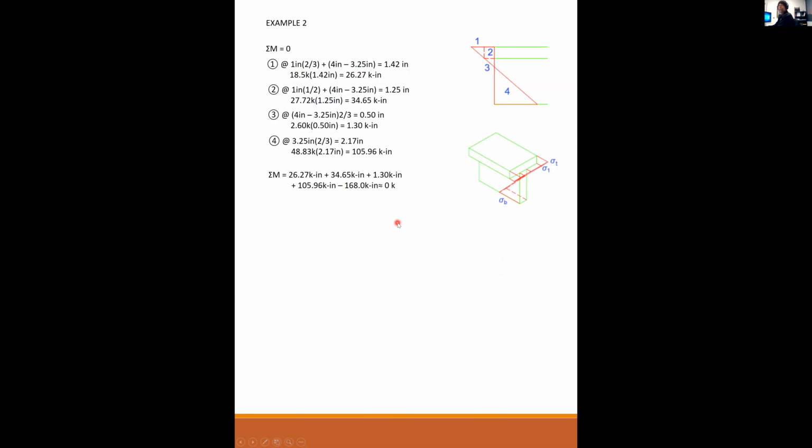Okay, and so the last thing that I've done here is I drew, kind of a bad angle, an isometric of the stress profile for basically this. So this, drawn to scale in isometric, looks like this. And again, the point to pick out here is that the neutral axis is right where it crosses that plane. I know that if I could do this in a solid modeler, I could rotate this for you, but it ended up being a bad angle.